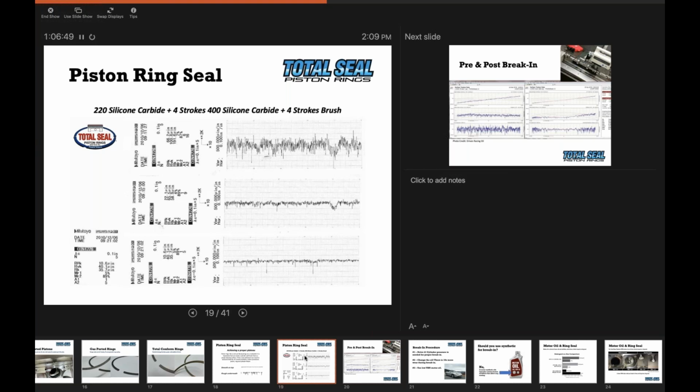Well, the nice thing is that with a gapless ring, because of that higher ethanol content in the fuel, the engine's going to run richer, right? It's going to tune it a little bit, and as you run more ethanol in the fuel, you will typically have to run a richer air-fuel ratio because of the amount of oxygen that the fuel brings with it. It requires that.